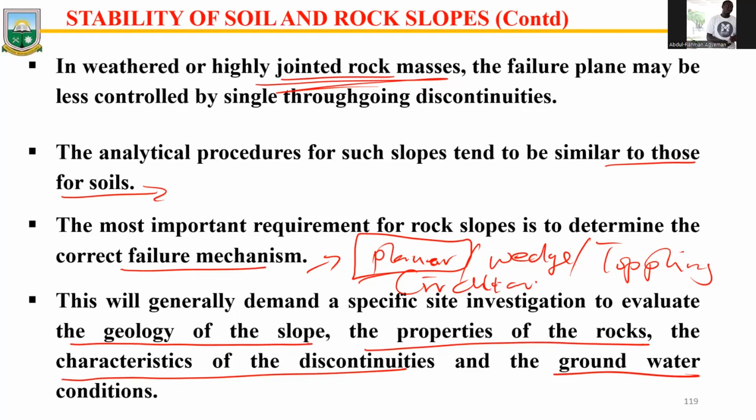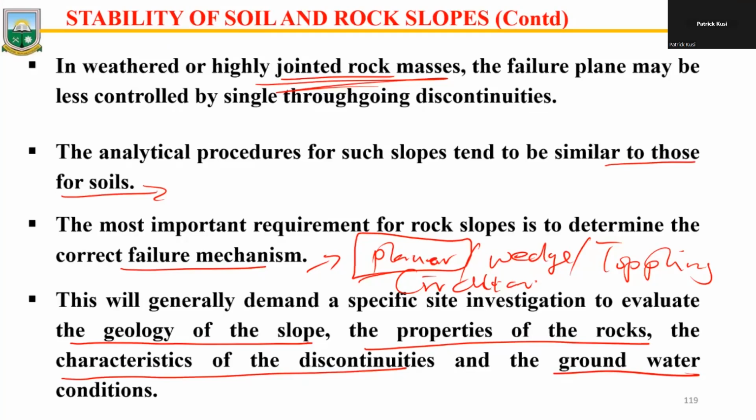Doc, if I can come in. Yeah, go ahead. Yes, and also when it comes to TSF design and construction, you also need to understand the foundation on which you are putting up your embankment, because that will set the base for whatever embankment you are placing on. So the foundation, the material properties, so that you can get the required compaction to set the structure on.